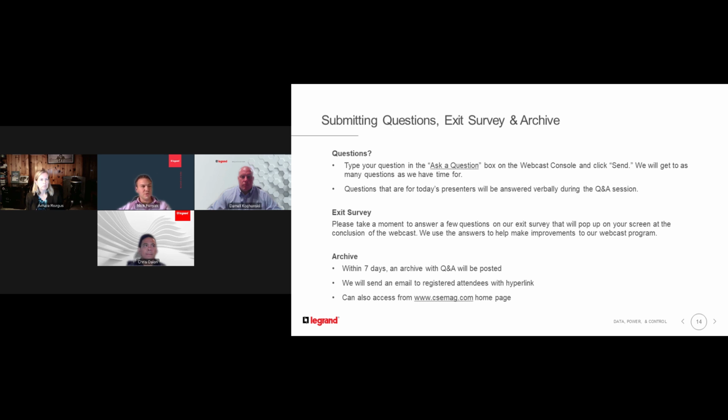Again, going back to the reuse of it, right? It is configurable from the standpoint of you could change your tap boxes in and out. So once you put a tap box in, you're not stuck with that tap box. If you wanted to change it or move it 6 feet down, it's very easy to do. You pull it out, drop it down on the bus, move it over, put it back in. So really simple on that side of things.